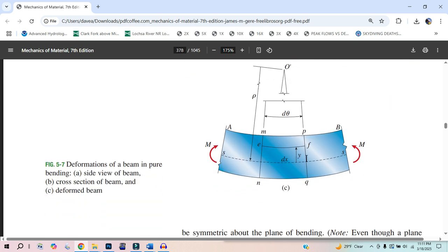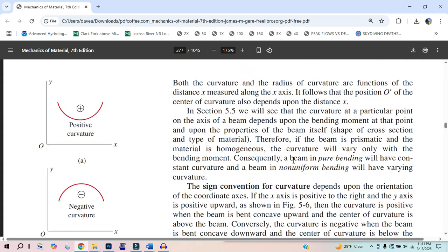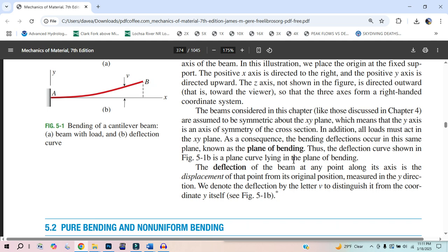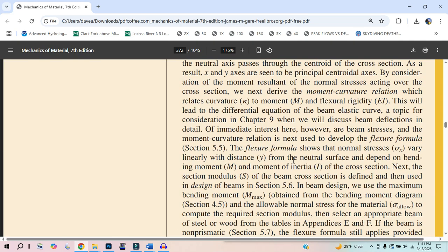And so here is the curved beam. This line right here doesn't stretch. Now, just because we know there's a point that doesn't stretch does not mean we know where that point is. Going through the proof, you actually show that if it's a rectangle, it's going to be in the middle. If it's that trapezoid, it's going to be at the center of mass. Hell yeah.